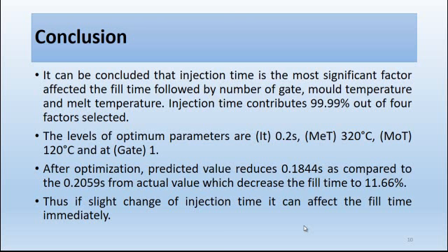After optimization, the predicted value is reduced to 0.1844 second as compared to the 0.2059 second actual value, which decreased the fill time by 11.66%. Thus, if there is a slight change of injection time, it can affect the fill time immediately.